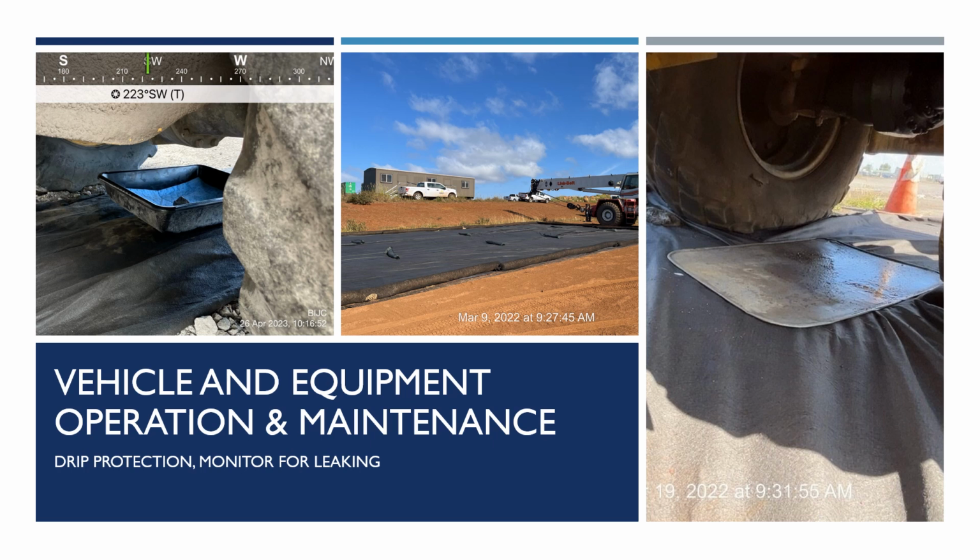Vehicles and equipment stored on site must have drip protection utilized under any locations which could be a source for fluid leaks. Paving equipment must have drip protection under the full footprint of the equipment. Drip protection measures must be impermeable to contain any leaked fluid or waste from reaching the ground below. Any equipment fueling, cleaning, or maintenance areas must be approved prior by AREE and designated on the project's BMP map.